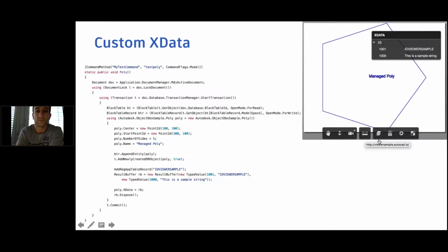So you basically can run scripts and .NET applications and Lisp applications and CRX applications on a DWG, and that might be something like, for example, updating a title block or exporting plotting a PDF file. And it's all online, so it allows you either from your desktop application to use this web service to create or modify a DWG, or from something like a mobile application or a web application.